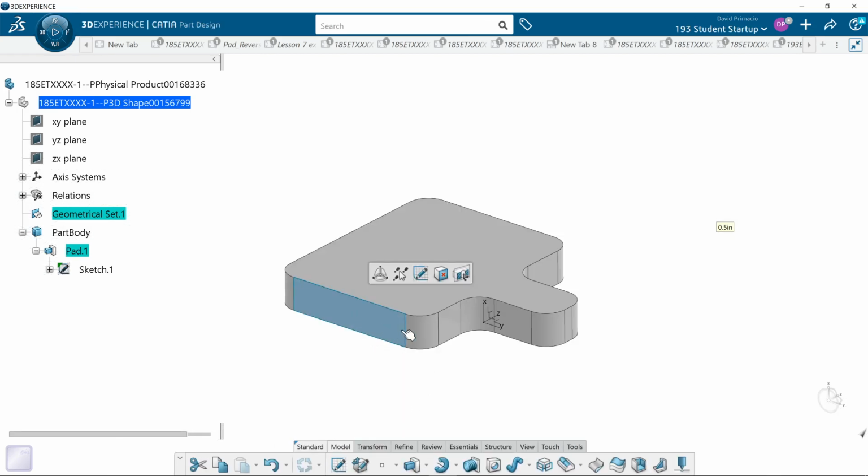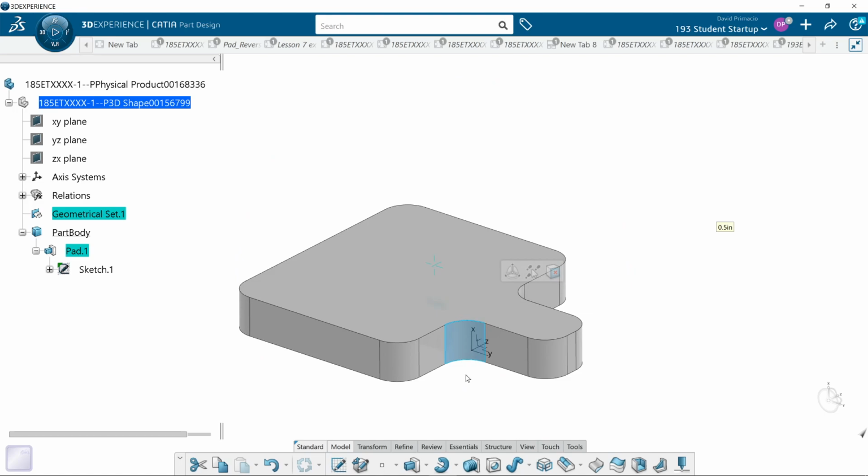So this face and this face are okay, but once I get in here with my 1/2 inch cutter, what's going to happen? It's going to chatter right here. Okay? So I have to change all these radiuses to 9/16, right? Depends on what you want, how you're designing it. Yeah. Well, for machining purposes, to get in and machine all these, I have to have them all 9/16. Okay. So I got to change this to be 9/16 and this to be 9/16. Otherwise, I could not machine it with a 1/2 inch cutter. Agreed?